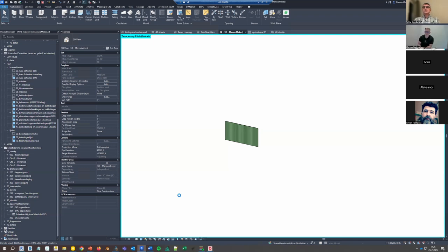And that's why the IFC schema, or any international standard, is used, because it doesn't matter in what tool you read an IFC, every tool will read it. Every tool will understand if it's a wall, the area is the front side. If it's a floor, a slab, the area is the top side. And if you just have some geometry with some data, you cannot trust it.